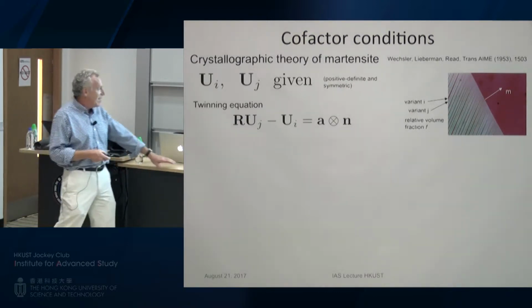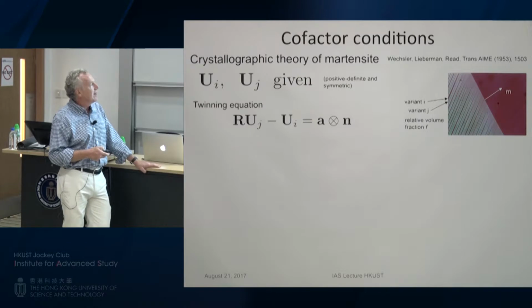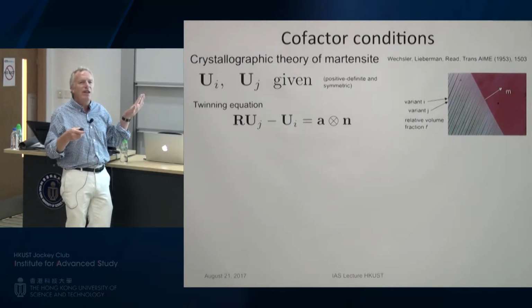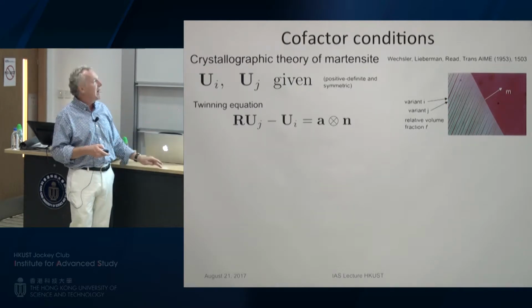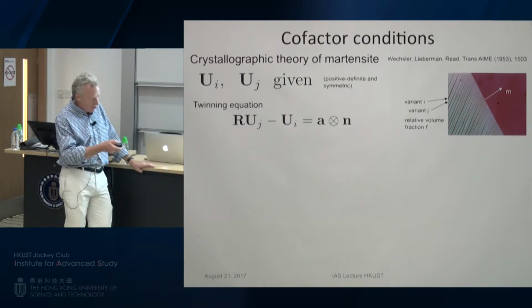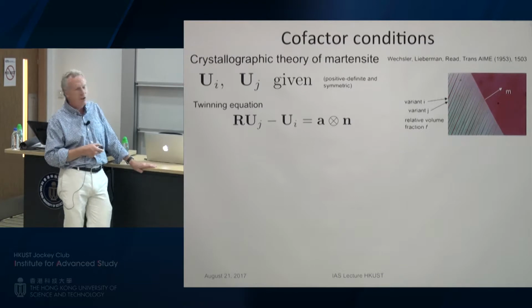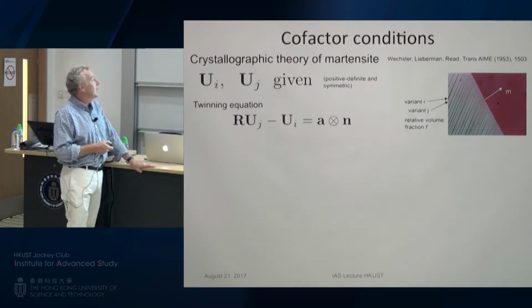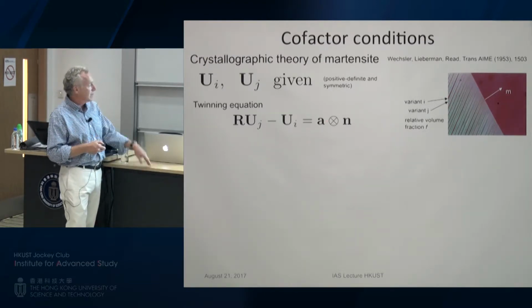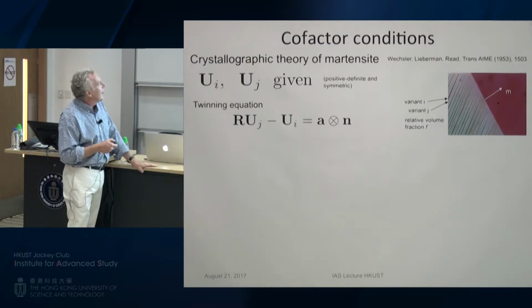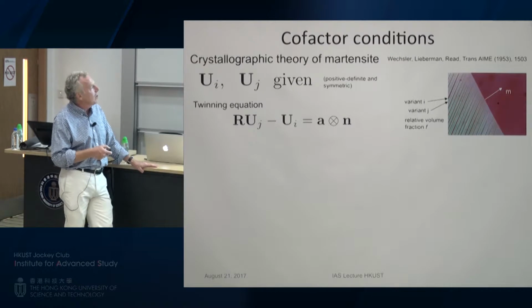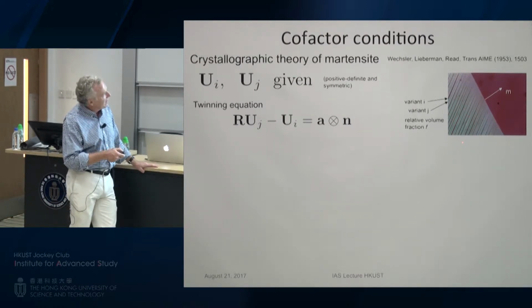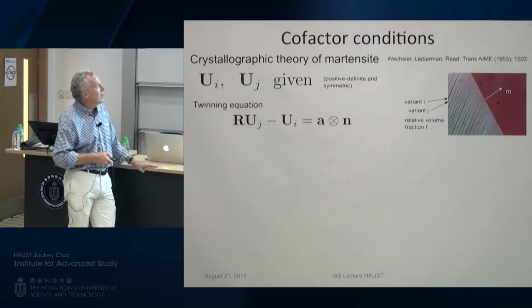Okay, so that's hysteresis, and once you see that, you can think, well, maybe there are stronger conditions than that, which would be called the condition of compatibility. And you can imagine there could be stronger conditions of compatibility that you could try to achieve. And to do that, I need to tell you a little bit more about the crystallographic theory of martensite. So, as I said, there were some bands here. There's some elastic transition layer. There's the austenite phase over here.